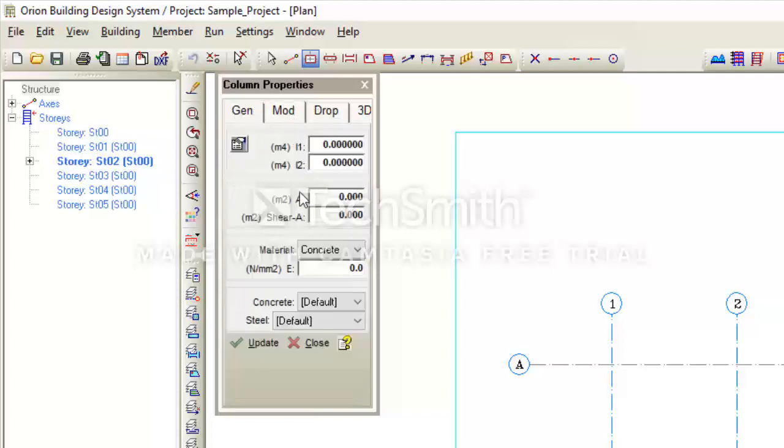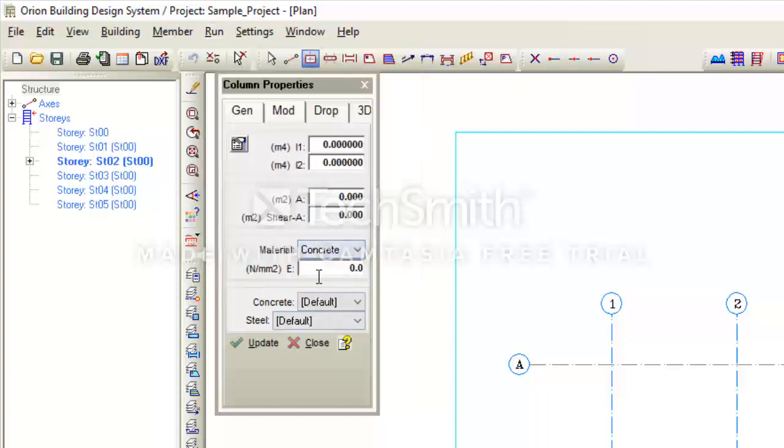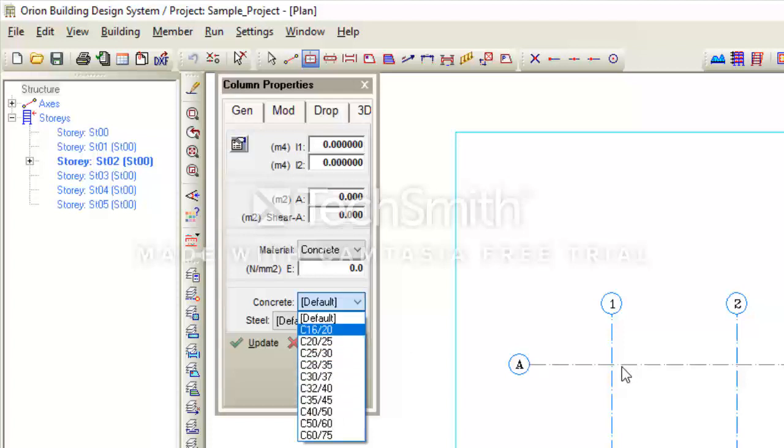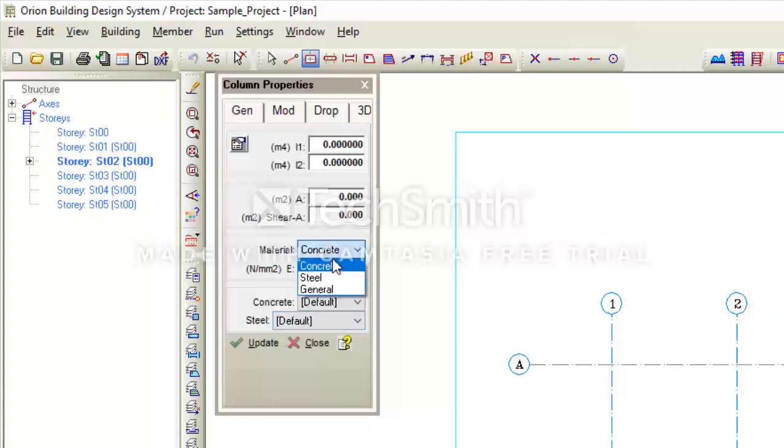On the material tab, you can denote the grade of your concrete. We've done a general setting for the concrete class in our run, in our build analysis in the run tab. We've specified that we want the columns to be 35. You can vary that value by specifying your concrete grade for this column, and for the next column you want to specify. You can also vary the value of your steel material. I advise you not to play with this.